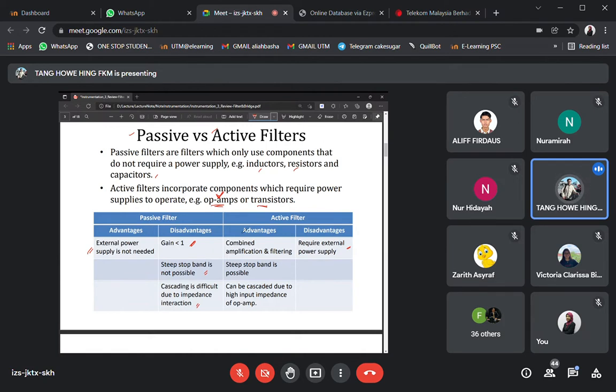We know that the inverting or non-inverting input of the op-amp actually has an infinite impedance, so it cuts out the impedance coming from the previous load. A passive filter doesn't have this feature, and therefore cascading different filters together could cause interaction between the loads, which makes your design very inaccurate.